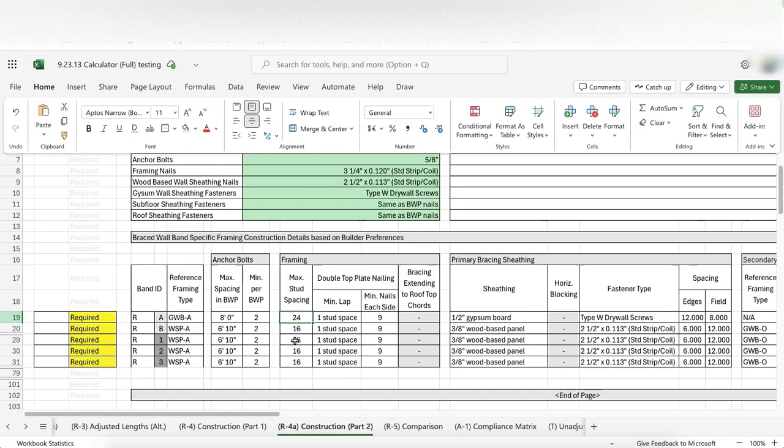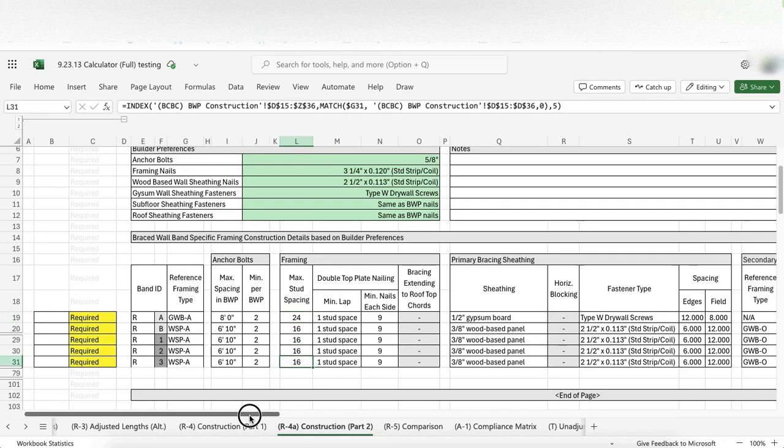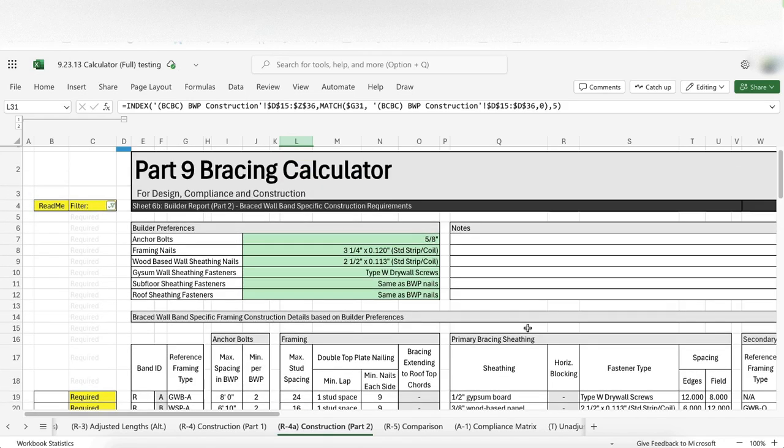So for example, with that example I gave with the cripple wall supporting a number of stories, instead of reflecting what is required for the bracing, we'd input information that produced the most restrictive circumstance, and that might be helpful because you might be a builder and build something according to this table, but it turns out that there's another clause somewhere that actually means you've done it incorrectly.